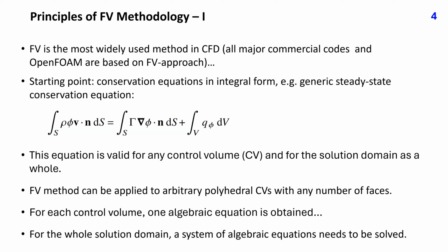Finite volume methods can be applied to control volumes of any shape, that is, polyhedra with any number of faces. The above equation is applied to each control volume and fluxes and source terms are approximated. The result is one algebraic equation per control volume in which variable values at cell centroids are unknowns. For the whole solution domain, a system of algebraic equations needs to be solved.